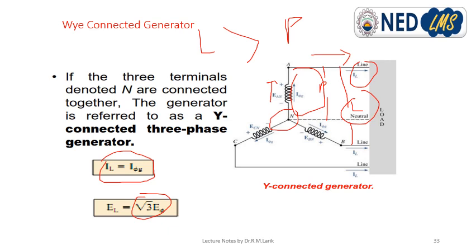Normally, the star connection is preferred in the auto transformer. Actually, an auto transformer means a one-winding transformer. So the windings of auto transformers are usually in a star pattern. If you divide the line voltage by root 3, you get the phase voltage. The phase voltage is reduced actually.